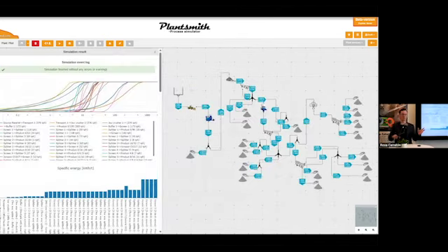So running the simulation, you get mass balance, energy balance, and cost balance. A few of the results that you get are the particle size distribution of the different streams in your production line. You get specific energy, which we use later on to allocate, for example, the electrical consumption. And in the blue boxes here, you get more information on specific stream properties, for example, F80 and P80, how it's entering the site, a quick indication of the particle size distribution.